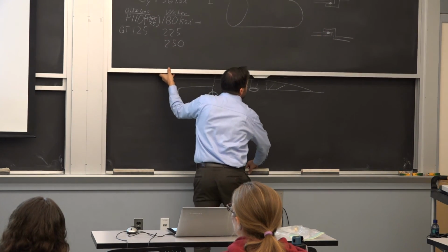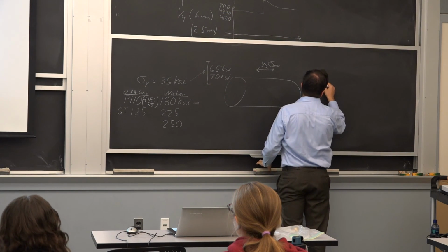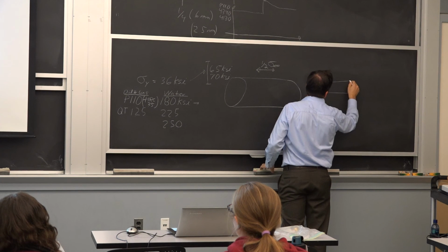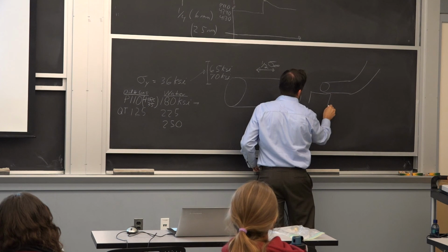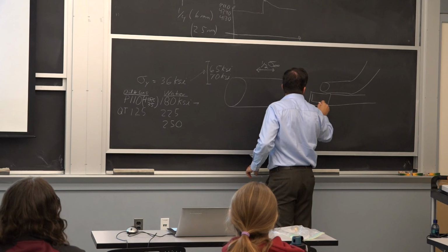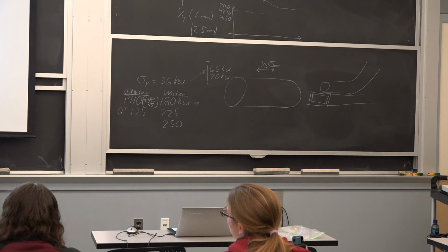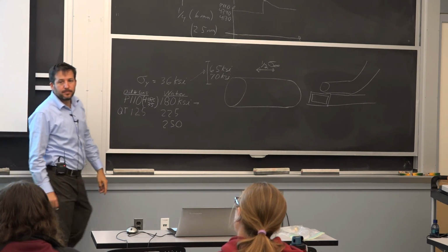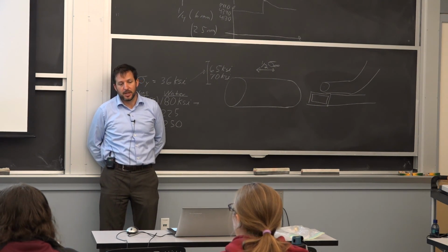Let's see. It's a round bar, and we can come back to it later. That's bent this way, and it goes over a tube that's rectangular. So what you see, this is solid, this is hollow. We're looking at the tube here and the bar, and this is the weld. You can see that the weld bead did not really penetrate into that tube, and that makes for a very low ductility joint. They had a lot of problem with this,